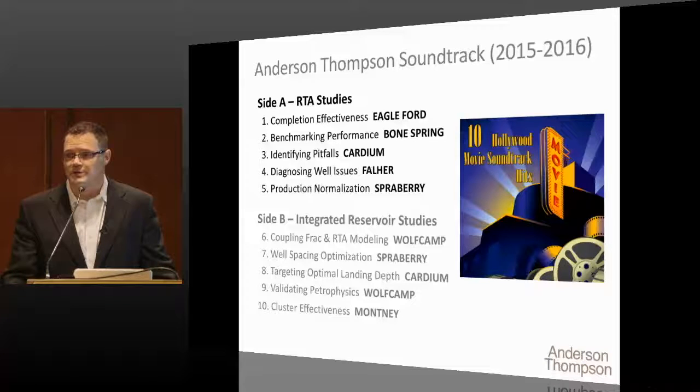Looking at well performance data and looking at rate and pressure responses and being able to identify if wells have uplift potential. Diagnosing sick or unhealthy wells that we might be able to solve with a clean out or a simple workover. And the fifth is well production normalization, and we're going to be looking at the Sprayberry for that example.